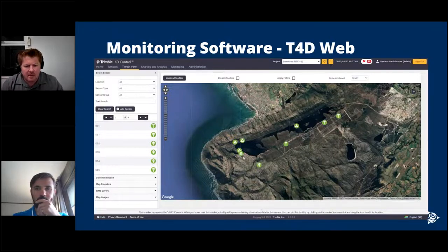So this is where the lower dam wall is. And some of our orientation beacons are up there, and that GNSS reference position is also up there. Steenbras upper dam wall is where this device is over here, and that's the piezometer that's installed over there. And then we've got the aquifer project, which has 3 GNSS stations at the moment, and then we actually have 1 cluster prism that we monitor because we can see this point from the total stations. We're just measuring that point as well using the total station. It's quite a long distance, about 1,800 meters or something away from the total station. Okay.